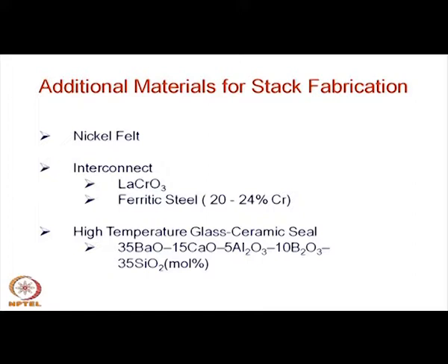That is the only thing one needs. In addition, of course, the other chambers or the manifolds and so on, some metallic manifolds are also needed for supply of the gases or taking out the exhaust gases and so on. But otherwise it is simple nickel felt for the tubular design. Whereas, in a planar design you need two important materials or two groups of important materials. One is the interconnect, which I have shown you earlier.